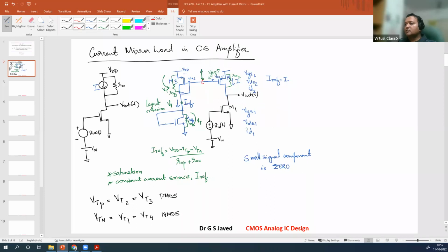Now, if you look at this voltage where you are connected, it is like it is connected to 2 diode voltages, right? This is one diode voltage, another diode voltage, and it is kind of independent of this operation. So you can use this to branch off multiple power supplies or multiple current mirror loads also.